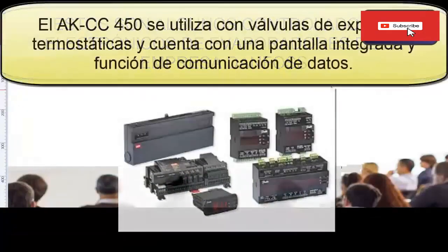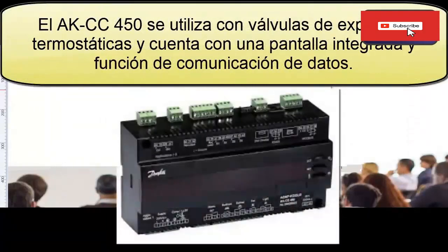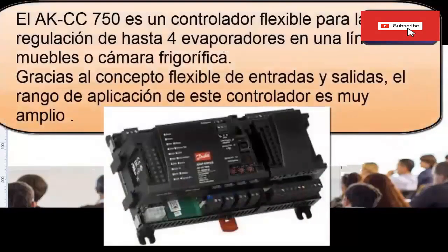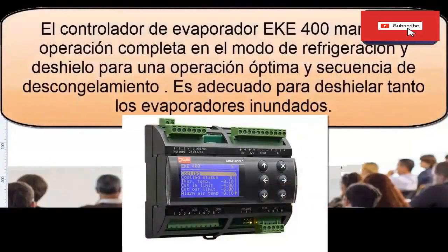A. Defrost stop temperature. B. Times for defrost intervals. C. Maximum defrost time. D. Defrost delay when turning on the equipment. E. Drip delay time. F. Fan delay after defrost. G. Fan start temperature after defrost. H. Fan status during defrost.